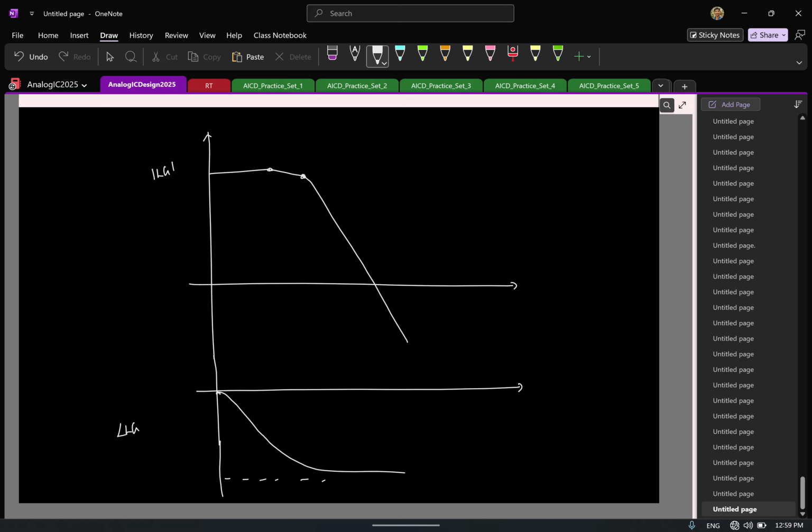So it means now if you check the phase margin without doing anything at this frequency, you see that the phase margin is actually very small. So now when we do Miller compensation, wherein we keep one pole much closer, other pole much farther, what we are essentially doing is this: we keep one pole here, basically keep the other pole here and do something.